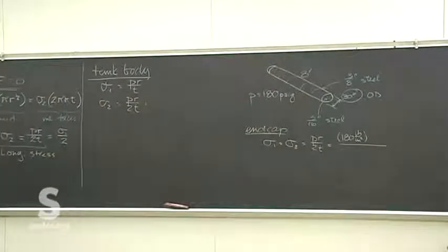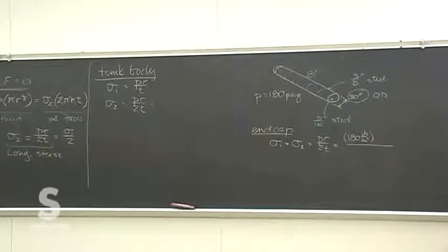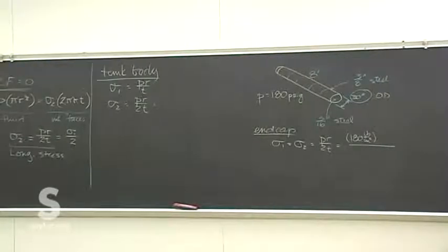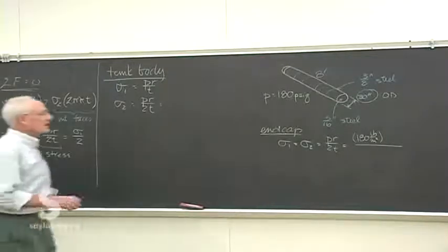Pressure 180 psi. What do you have for R? You had 14.84. What do you have? We'll get different things for R. You have 13 point something. We're all over the map. No, that's the outside diameter. Minus 5/16. Oh, okay. Yeah, for the end cap, it's 15 minus 5/16.